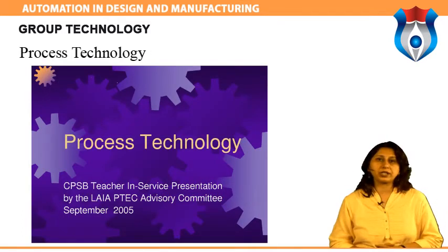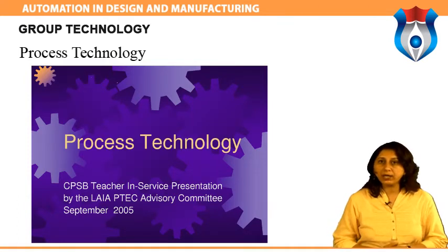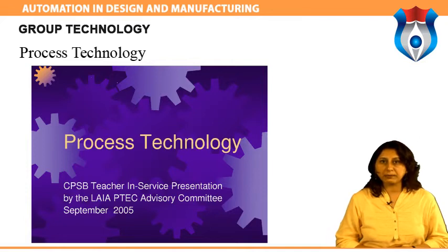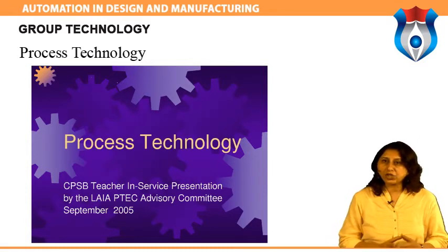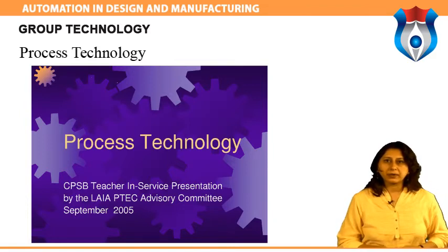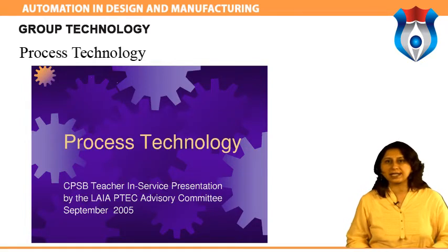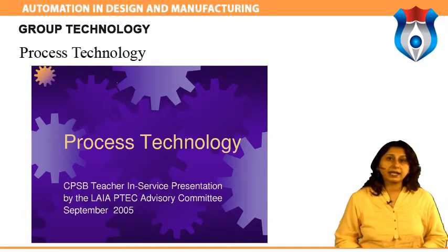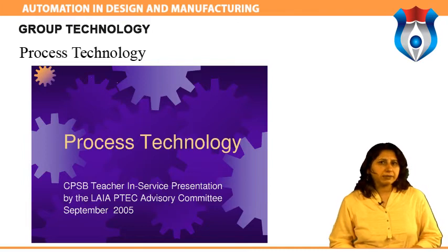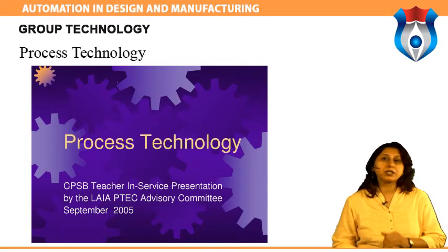Process technology. GT work cells usually favor smaller scale, less automated process technologies that change over easily and fit the lower volumes. Machine shops are an exception. CNC machining fits very well with GT cells. CNC technology does not really cut metal faster. It reduces setup and combines operations.